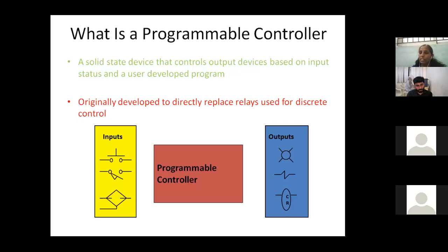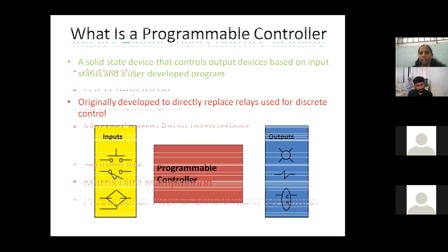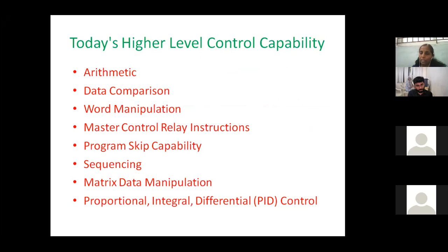Or else, if the temperature in the room is greater than 50 degrees centigrade, I need to turn on the cooler. If the temperature is greater than 70 degrees centigrade, I need to turn on some other indicator output device. So in this case, you have to perform a compare function. In all the control functions, you have to perform only arithmetic and logical functions. That is the way in a controller, not simply for a PLC, since the PLC consists of a microcontroller.